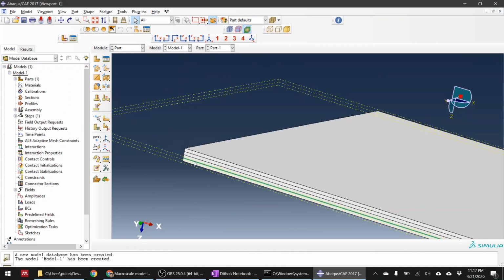Remember, in Abaqus the Hashin damage can be used for a continuum shell or conventional shell. When you're doing conventional shell, your geometry has to be a plate geometry. If you want to use continuum shell, your geometry should be a solid geometry like this. Even though this is solid, the element is not a 3D solid element, but a continuum shell element. So the kinematics is still two-dimensional, but the appearance is a solid 3D. They don't have solid element kinematics, so they still work like shell elements.